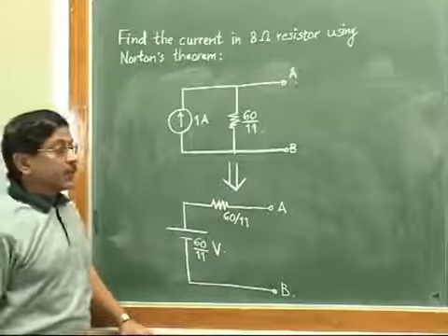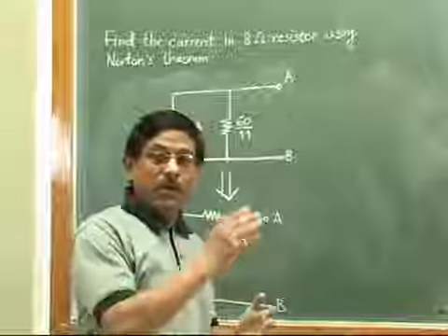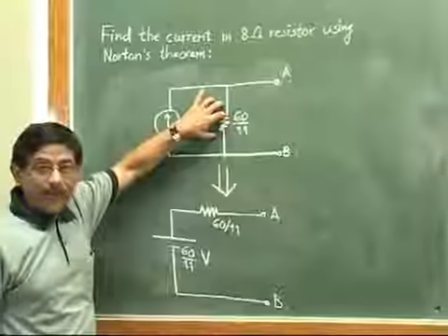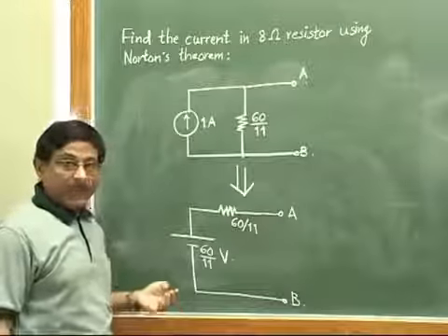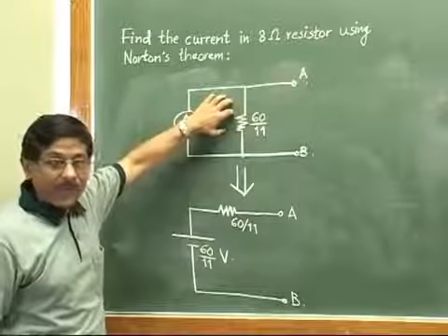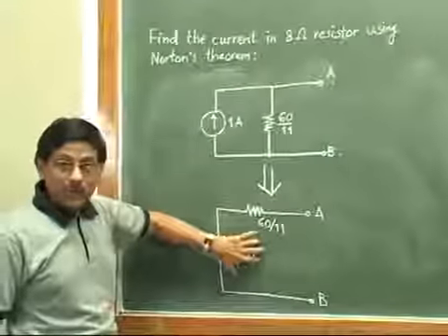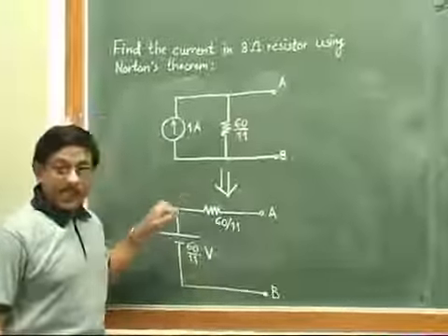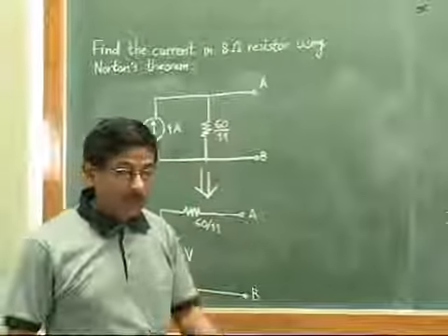That means if you solve any such problem with either Thevenin's or Norton's theorem, and you convert the equivalent circuit you get into the other type of source, for example you solve with Norton's and convert to an equivalent practical voltage source, you will get exactly the Thevenin's equivalent circuit. That's why it is said that Thevenin's and Norton's theorems are complementary to each other.